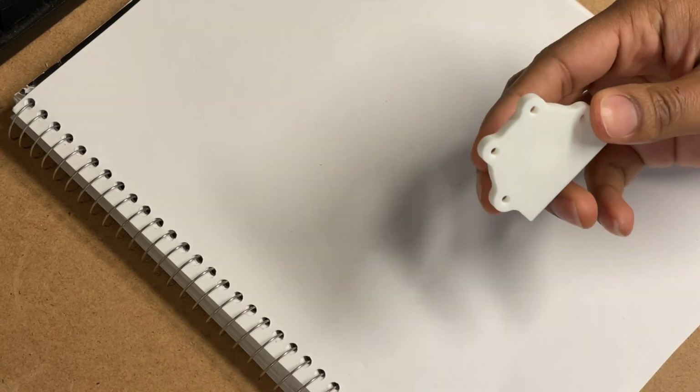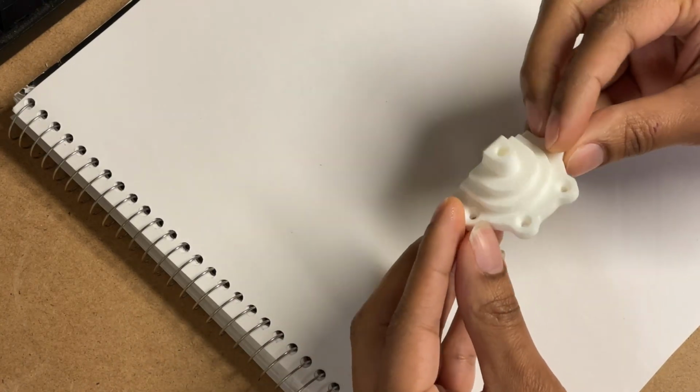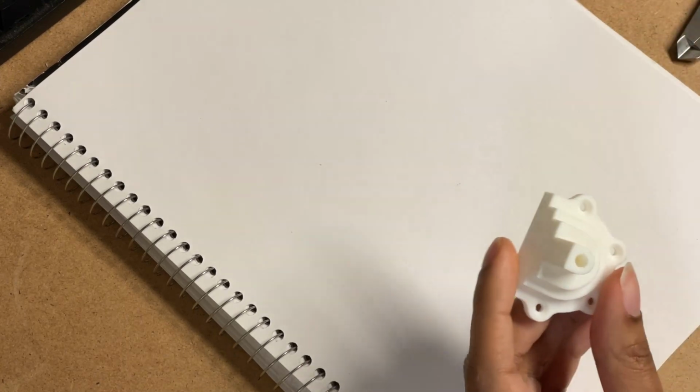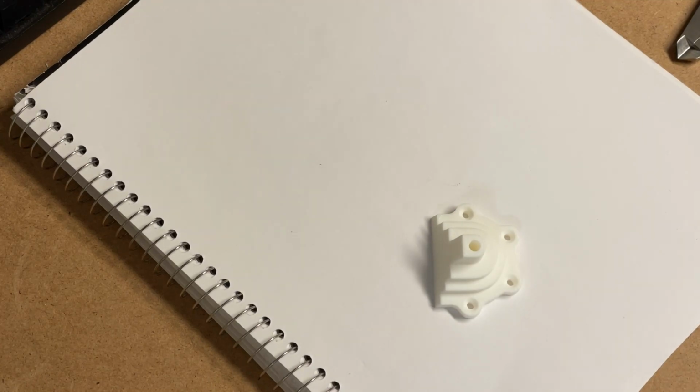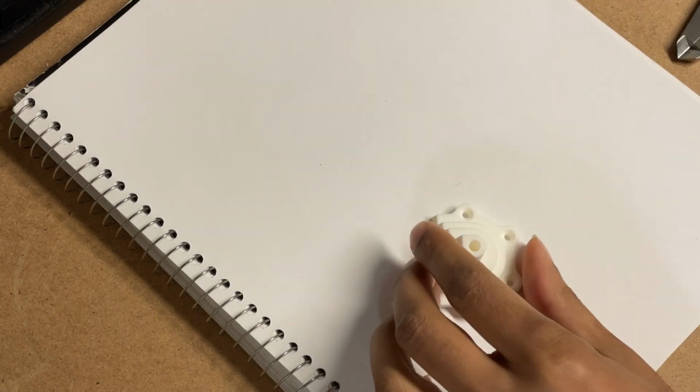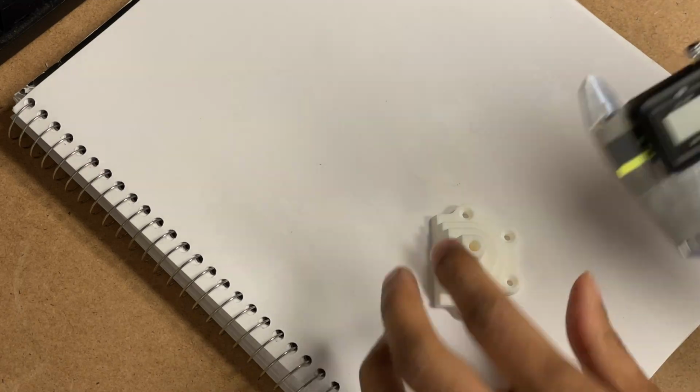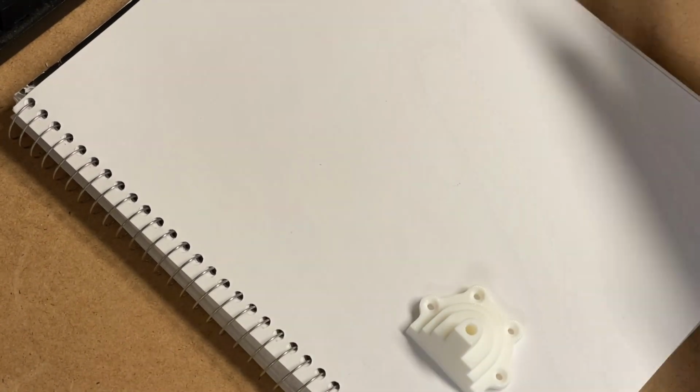So before we actually reverse engineer this part and produce a CAD model of it, we're going to create a sketch. We're going to draw it up on paper, just because we don't want to disrupt our CAD process by having to stop all the time and pick up our measuring tool and pick up our part and then come back to our mouse and back and forth. It can really slow your process down. So first I'm going to create a sketch.